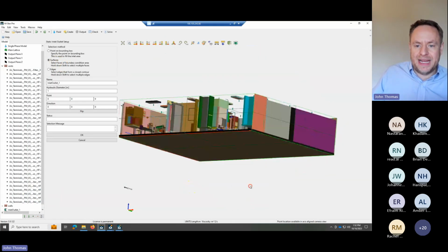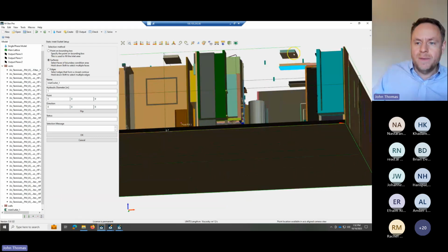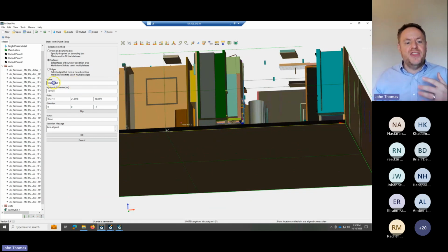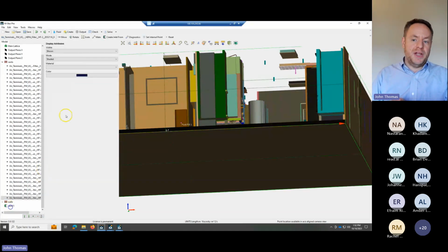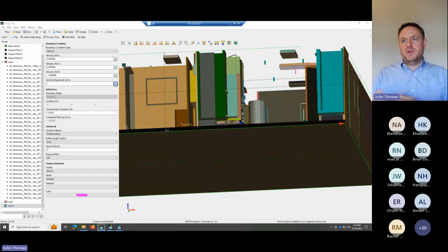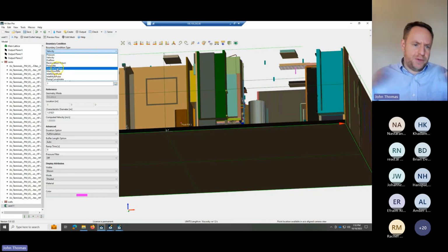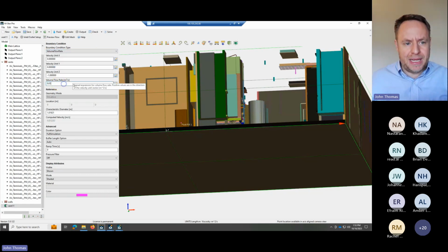I'm going to go ahead and start selecting these events, as it were, and I'll click on them and start defining what error is coming in which one. And again, this can be wired up with a PID controller system to govern how flow moves as a function of, say, concentration or some sort of controller logic, whether it be temperature, whether it be species, whether it be CO2, etc. I can, again, specify flow rates, velocities, pressure, whatever it might be. I can specify constant time varying values.